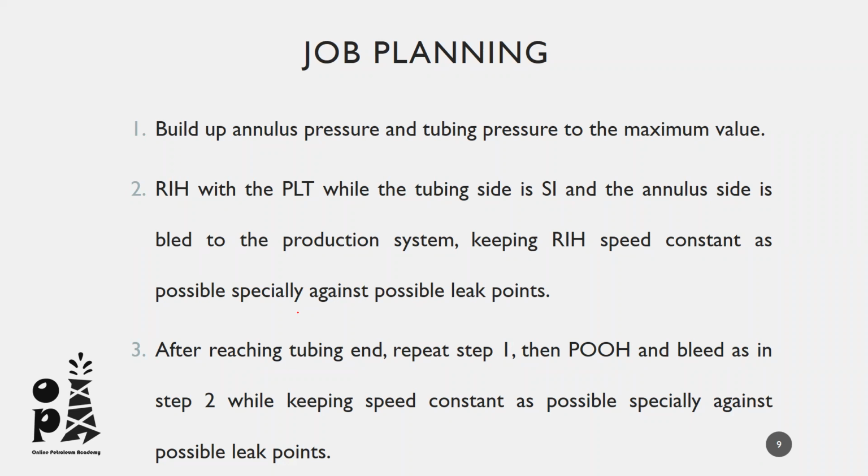The final program of the BLT will include both the objective and the selected tool string and the deployment method and the detailed sequence of the operation. This is a really important part of the design because you are looking for a leak. So you must condition your well to be able to detect the leak points.